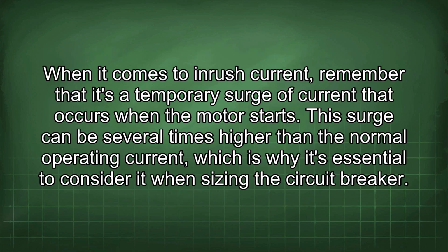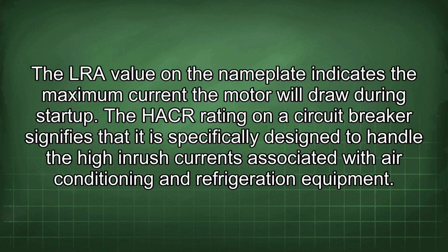When it comes to inrush current, remember that it's a temporary surge of current that occurs when the motor starts. This surge can be several times higher than the normal operating current, which is why it's essential to consider it when sizing the circuit breaker. The LRA value on the nameplate indicates the maximum current the motor will draw during startup.